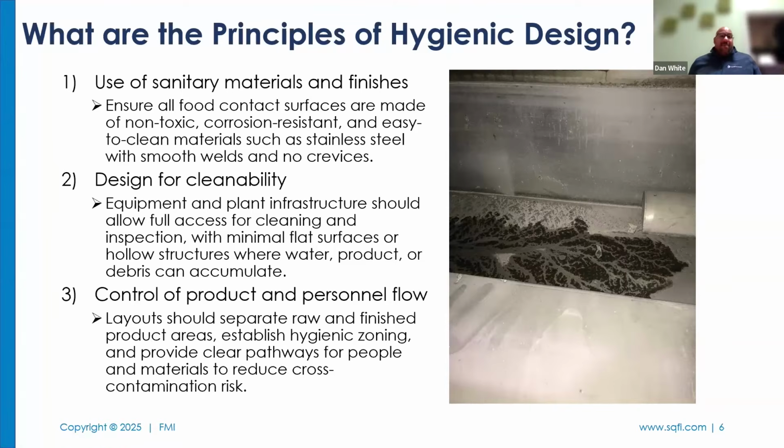And at the end of the day, it broke. It leaked non-food grade oil into product, and I had to go back to the last full wash that I did, which was 10 days ago. So I lost 10 whole days of productivity on one production line for a couple different failures. Obviously it's the oil, but not replacing the deflector screen on top, that's another one. That cost in excess of, I could have bought 100 gearboxes for that one mistake. So when it comes down to hygienic design, it's no laughing matter. Yeah, and it can cost you greatly. Exactly. So ouch, that one hurt.